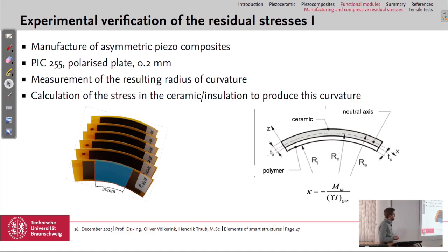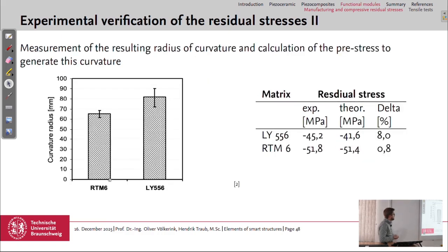And this curvature can be measured, and then from this curvature we can calculate the residual stress. It's really a residual stress, not a pre-stress, because it's not an external stress, it's internal.